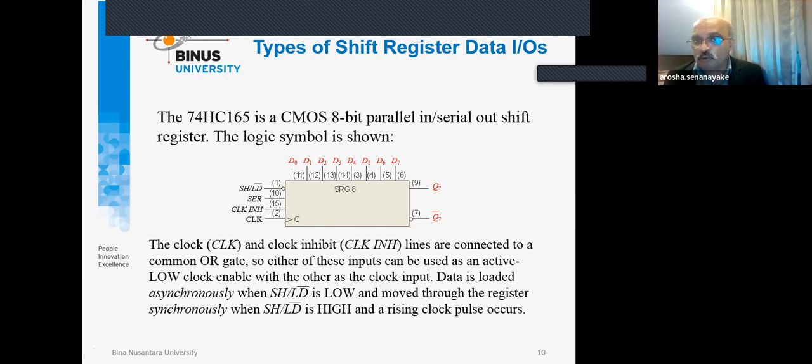And then, importantly, when it comes to D-type flip-flops, you can see that this is a shift right register, an 8-bit shift register. Through Q, what we get is exactly the data entered, and through Q bar, we get the inversion of the entire data set.